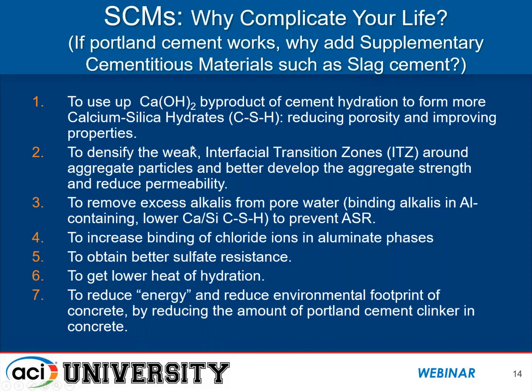The SCMs also have an impact on densifying what are called interfacial transition zones around aggregate particles. There's usually a weak zone around every aggregate particle where there was water originally in the mixing when the concrete was fresh, and the cement grains can't pack up against the aggregate grains very closely. And the secondary reaction of these supplementary cementitious materials will densify this zone and help to better develop the strength of the aggregate and reduce the permeability along these pathways.